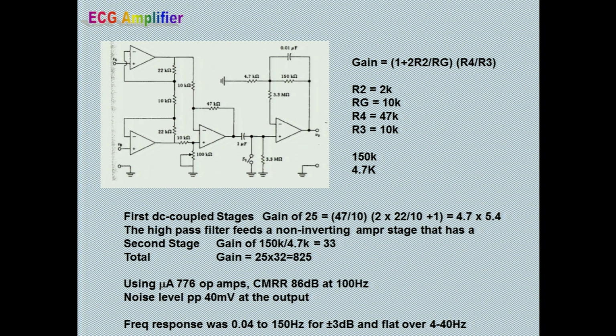This is to be done individually with the inverting, non-inverting amplifier, using the instrumentation, then differential, because that way you can avoid the loading of the system. So first is the pre-amplifier stage, then the differential amplifier, then the high frequency filter, then low frequency, and then another second stage. Actually 3 stages if you count.